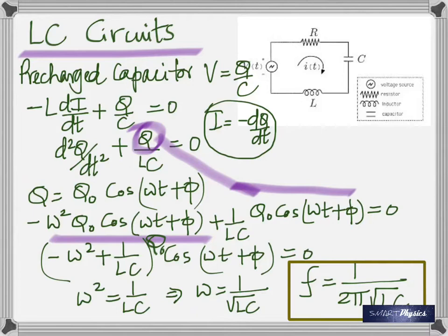This is the knob that you're turning. So what you're actually doing is increasing the overlapping area, which changes the capacitance. Then your radio gets tuned to a particular frequency and you get the station that's broadcasting at that frequency. So we're getting into all that.